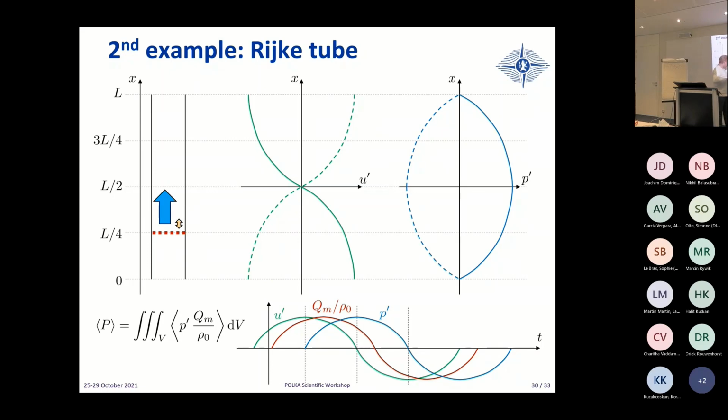And the time lag is actually bringing this heat transfer with a certain time delay with respect to the velocity, and this brings it in phase with P prime. And that's what you need. And that's the reason why this is working.